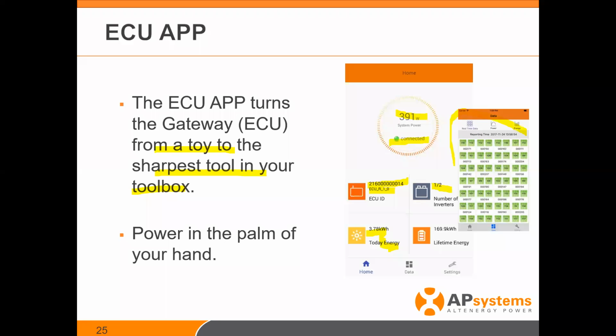And you'll be able to see on the application if it's installed, if it's communicating, if there's AC applied, and if it's producing power, right from the palm of your hand, without internet. I want to make sure that's very clear. When you're on site setting the system up, the gateway used to be the thing that you did at the end of the job. You'd get the rails in, put the inverters in, put in the modules, run the electrical down to the box, get everything tidied up, and then power up your gateway.